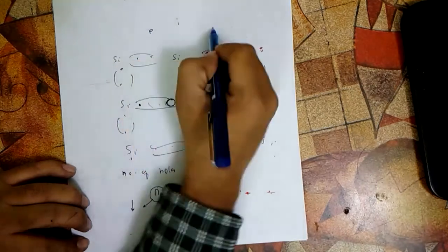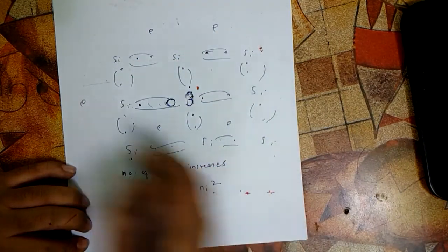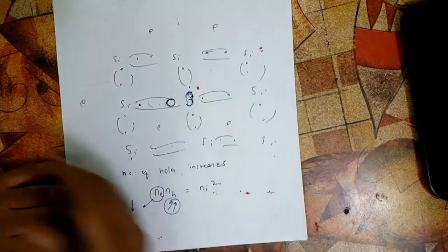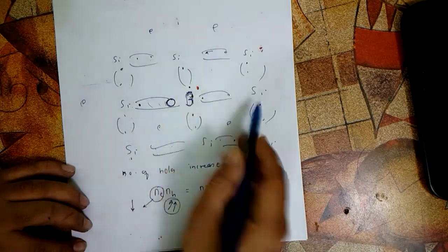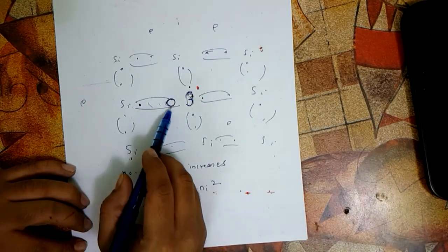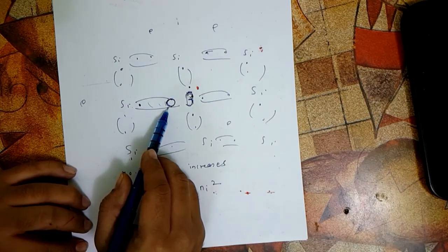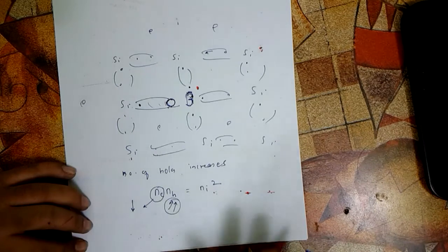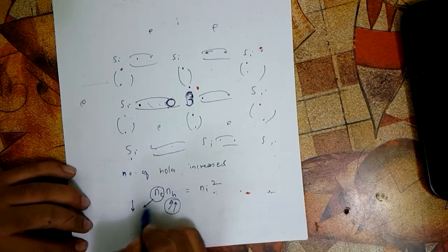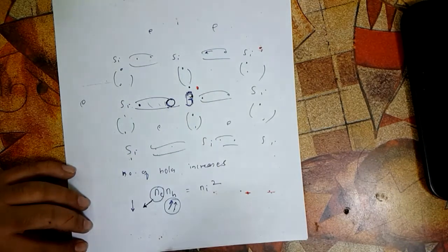Because we know that those free electrons are hovering all around the entire silicon crystal, and while traveling and moving randomly, the probability that they encounter the holes and combine with them is large. That's because more and more holes are available, so there is more probability that they will go into those holes. And so this Ne decreases. So Ne decreases because of electron recombination with holes, and holes increase because of more supply by boron atoms, but